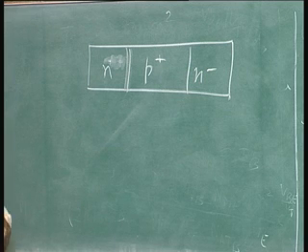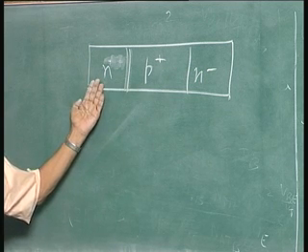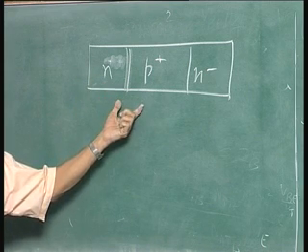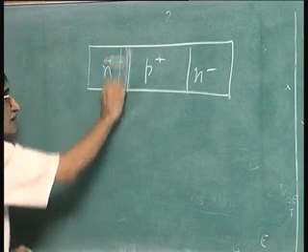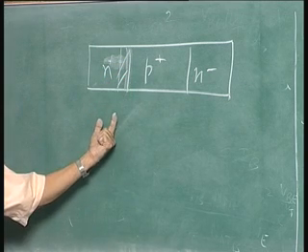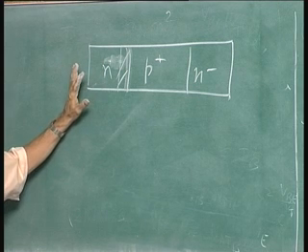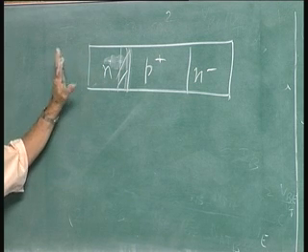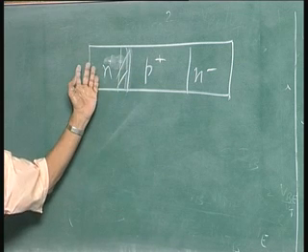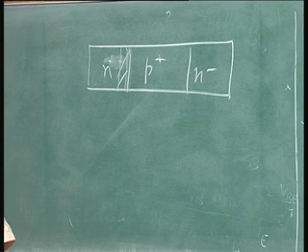Now, you see the whole thing is reversed. Base is doped much more than the emitter. Total integrated doping in the emitter is lower than the total integrated doping in the base. I can have this depletion layer going up like this, a wider depletion layer, and CTE will go down if I am able to decrease the doping. But my worry will be, if I reduce the doping here, if the band gaps are the same in the two regions, emitter efficiency will go down, and you will get a very poor transistor.